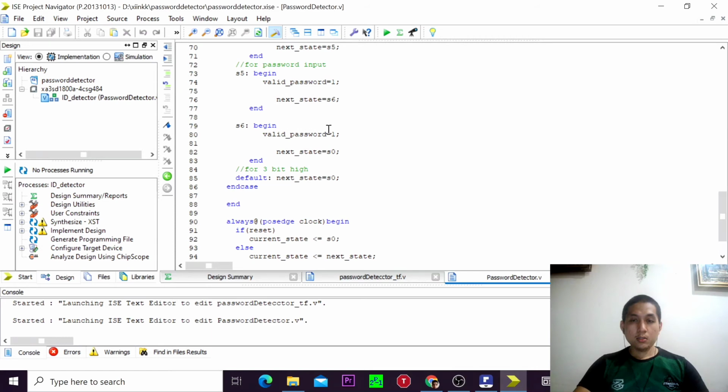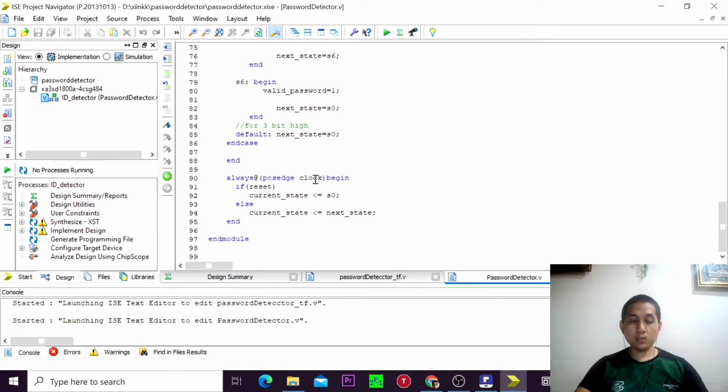So each bit that we have entered will follow the master clock of the positive clock trigger. It means when we enter 1011, each bit 1, 0, 1, 1 will be taken as input at the positive edge of the clock, right?